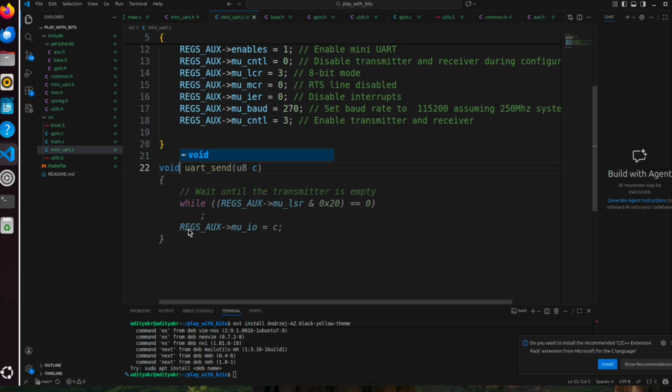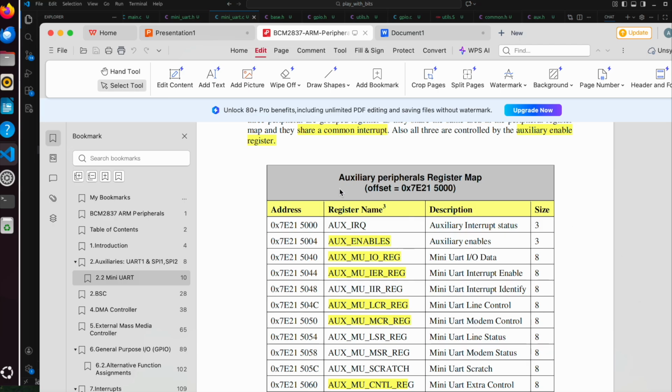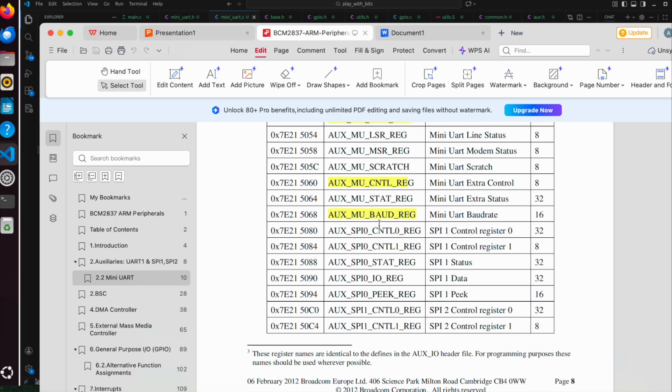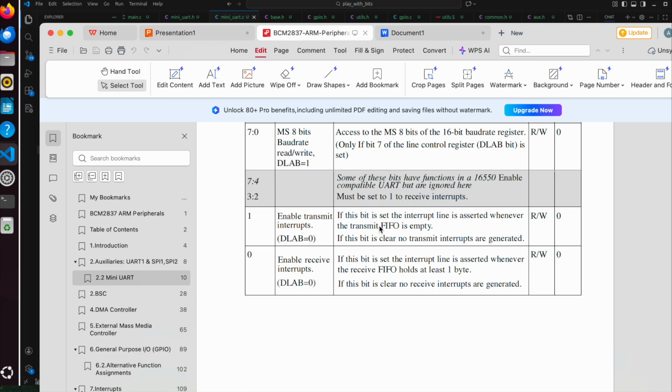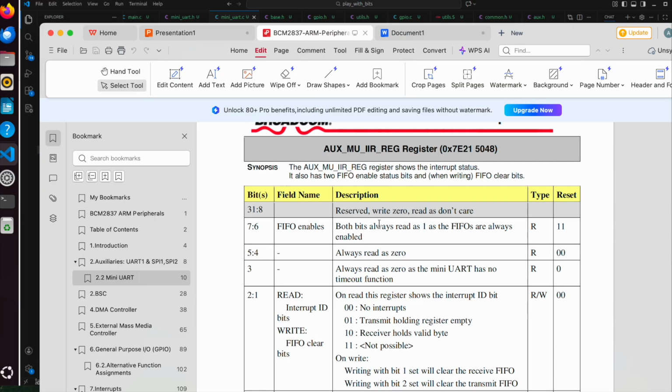Okay, so this one also it is giving, so basically AI is enabled, right? That's why it is automatically reading. So I will explain why it has written like this. Here we are trying to read the LSR, which I have told you about, a way to find out whether the TX FIFO is ready to accept 1 byte or not. So we read it, and we are checking that particular bit should be 0, then the while condition will become 1, then we are writing.